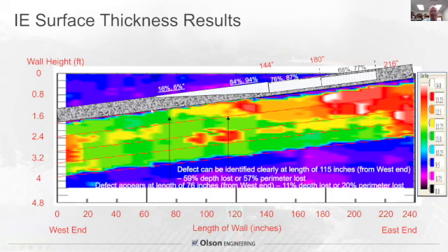Okay, so what do we see? In a side view of the data, where the scale on the right, the green is the normal thickness, and getting away from where it's grouted, you can see four ducts are stacked together. The top duct had these voids created that you can see. And you also see in the color scale how it got thicker in those zones where the void existed.